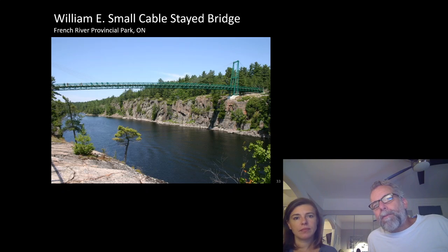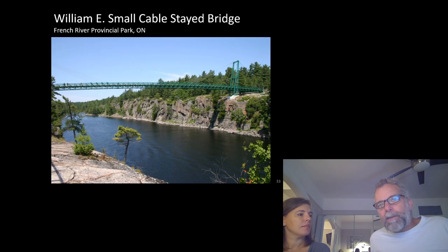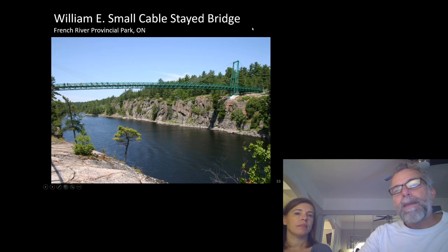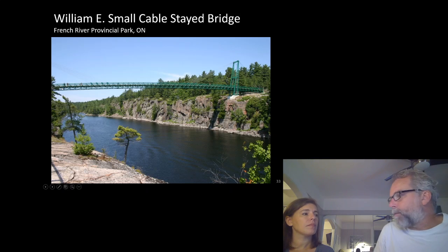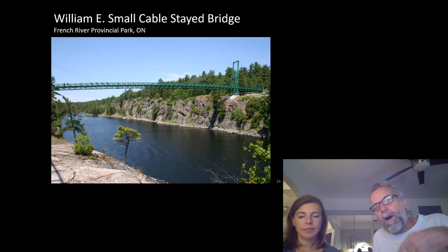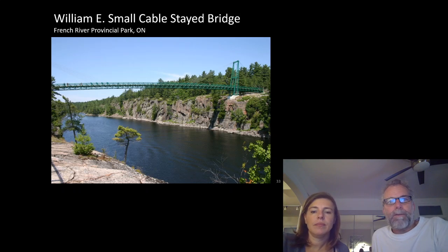Now, where the previous suspension bridge was not controlled by vibration, and when you walk across it, you can feel it, this one is controlled by vibration. So this one is a snowmobile bridge. So there's vehicles going across this all the time in addition to the pedestrians. And so it's vibration controlled. The cable stays are tremendous for adding strength, but this is a truss. And the truss gives it bending stiffness, so that it's not behaving like a funicular form.